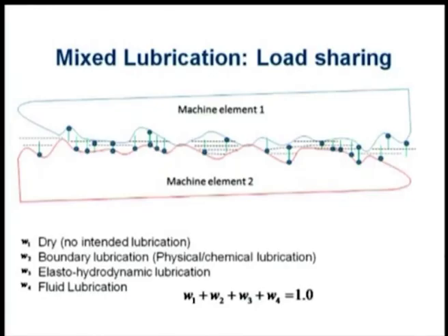If we are using a thick lubricant and operating at a higher speed, the friction will be on the higher side. That was also indicated by the Stribeck curve. If the sliding velocity is higher, and that too in the fluid film or hydrodynamic lubrication mechanism, the coefficient of friction will be on a higher side.